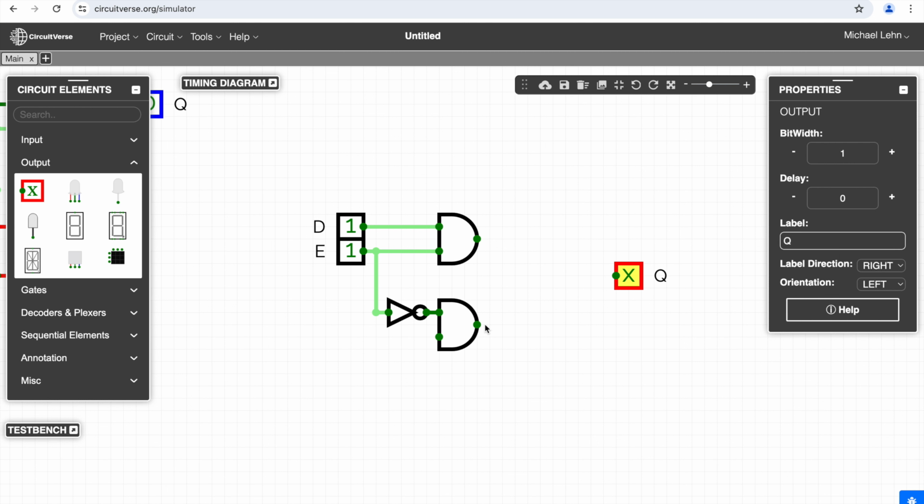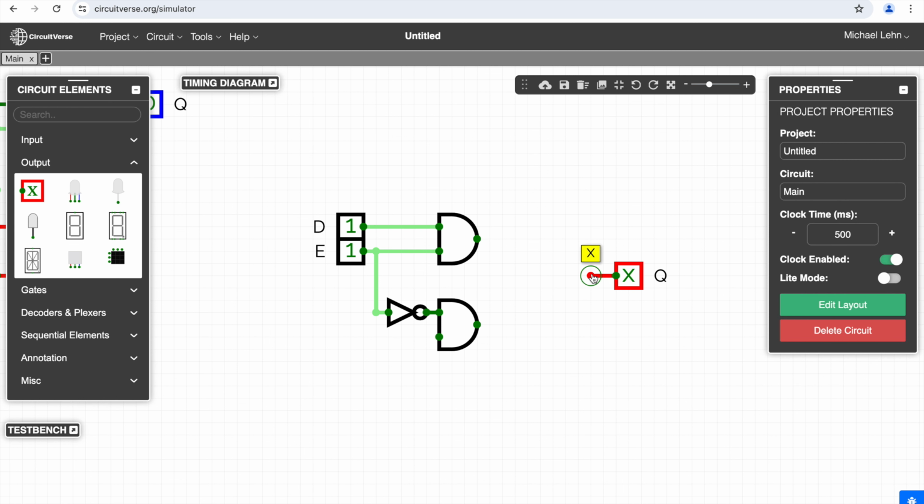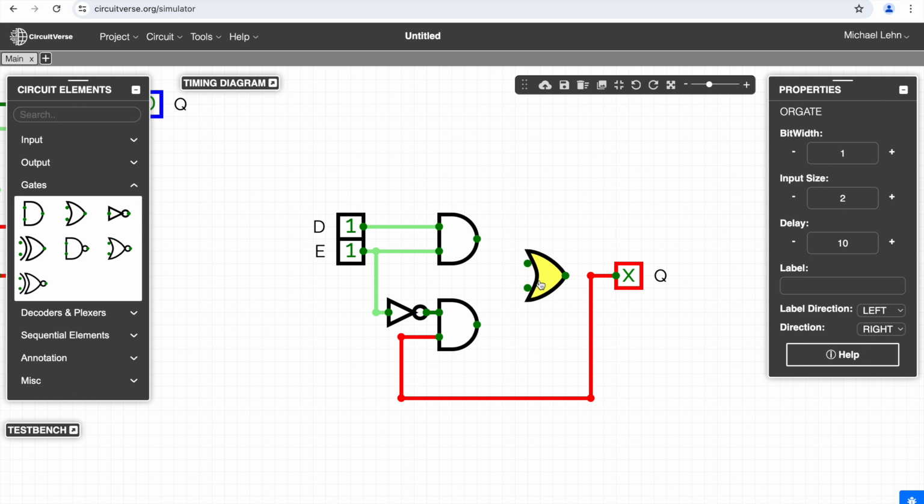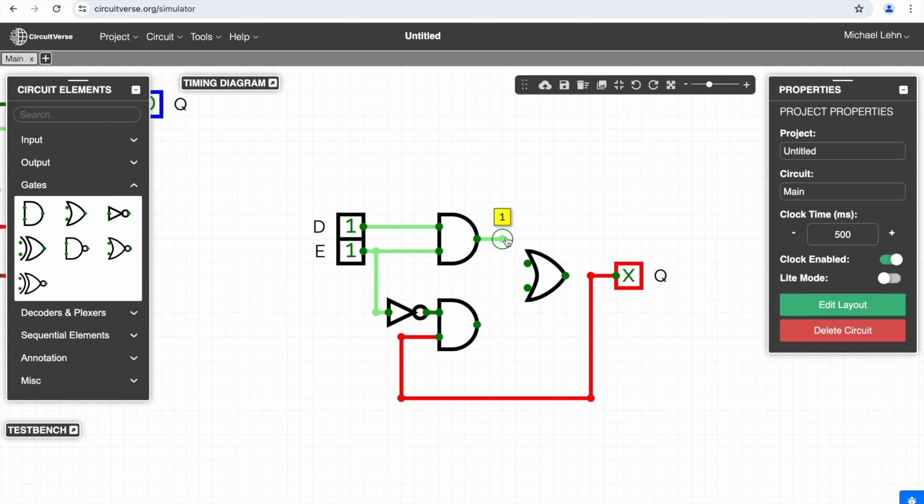So that simply would mean that Q is used here as an input. And then we had an OR, which is basically just connecting these 2 outputs. And the output of this OR equals Q. And then we have this implicit equation realized with AND gates, OR gates, and a NOT gate.